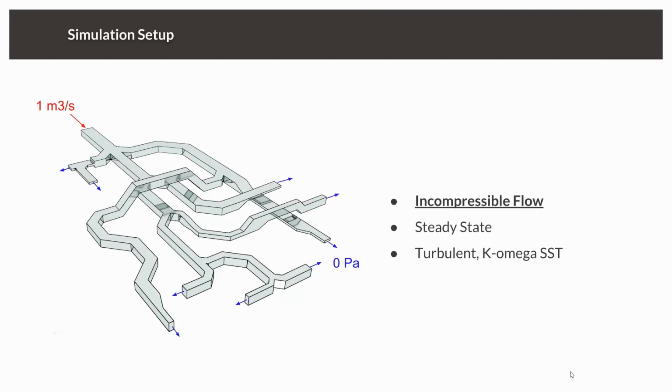Let's say this is our ducting system. We're going to use the fan for this, which we also find on BIMobject, and directly at BIMobject we can access all the data, and one of the data we need is the flow rate provided by this fan.